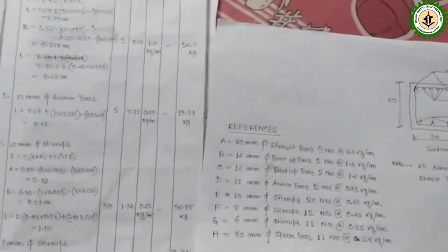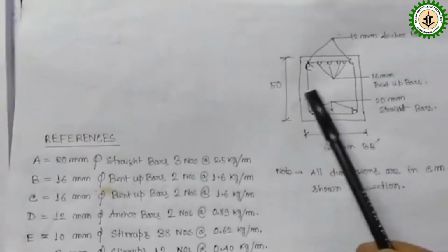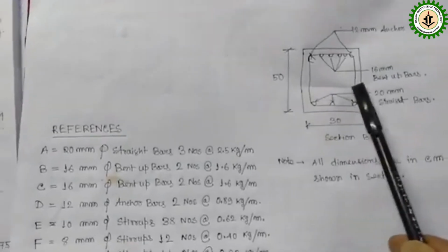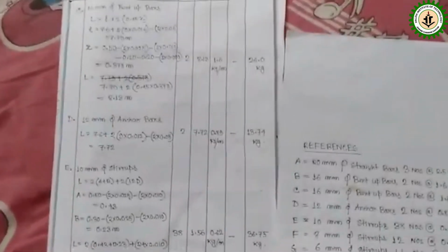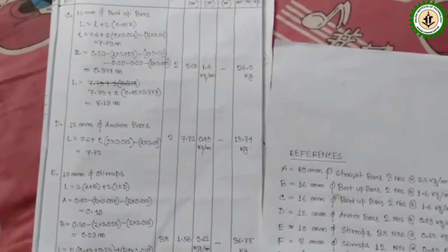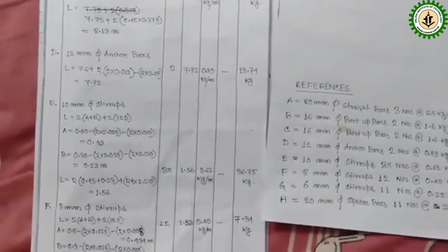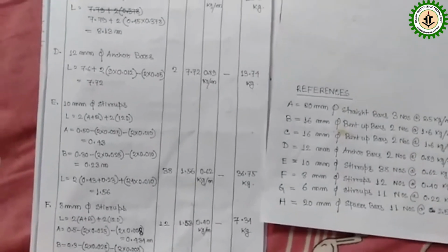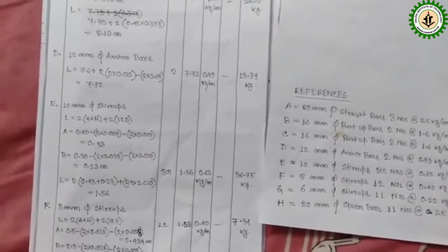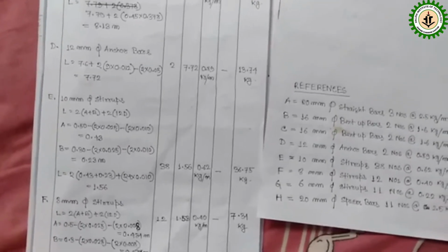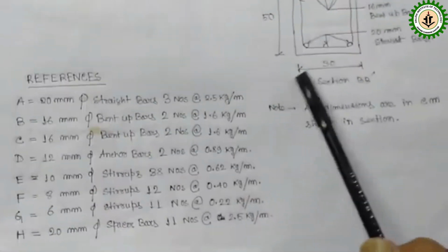Now for the horizontal B length, that dimension for this section is B. For the horizontal B length, we have to deduct the same cover area and same stirrup diameter from the width of the beam. So here the width of the beam is given here, 30 centimeter, that means 0.30 meter.